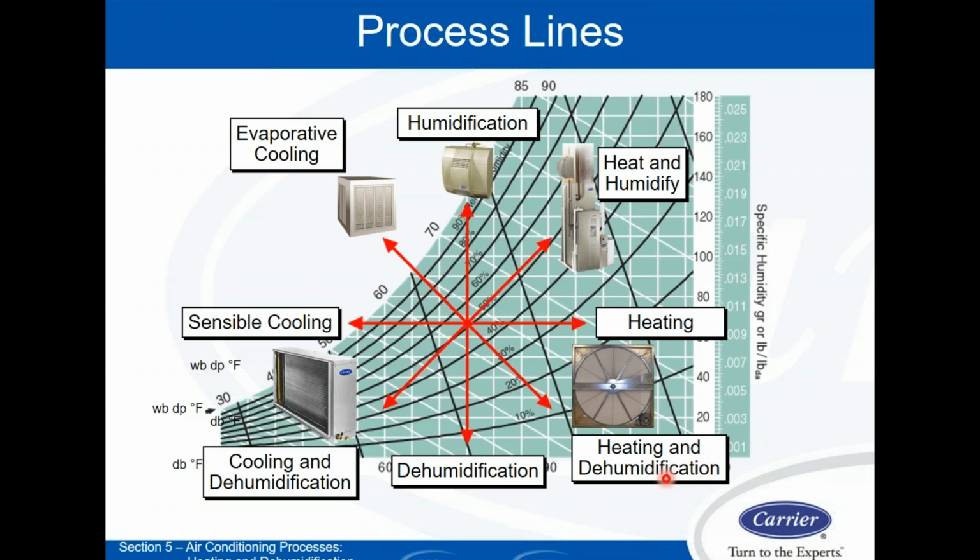So sometimes you'll dehumidify well below the dew point that you otherwise wanted to pull a lot of moisture out of there, and then you have to reheat it to temper it back up. So excellent point, Doug. If my brain just stops thinking of it as heating and dehumidification on the slide, and we think about it as dehumidify and then reheat to temper it back up, that is when we would in fact use this process line. Excellent, Doug. Love it.